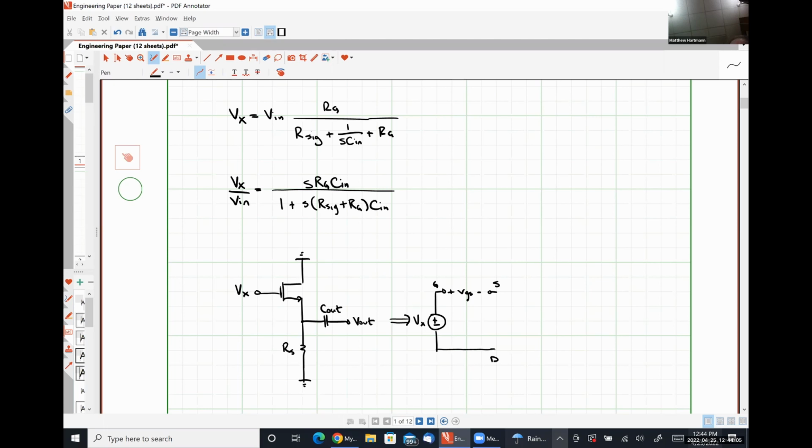Between the drain and the source, I should have my dependent current source, gm VGS, where the current is directed as flowing from the drain to the source. We're neglecting channel length modulation as we have in all of these discrete problems. My resistance RS occurs between my source and my ground, which is my drain. So I'm just going to put RS in parallel here.